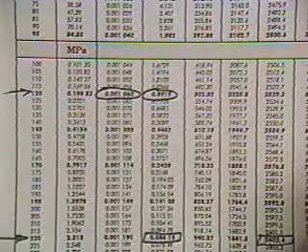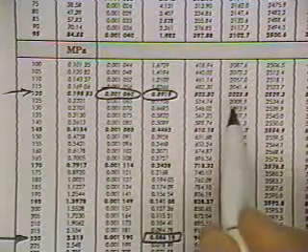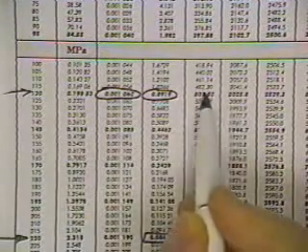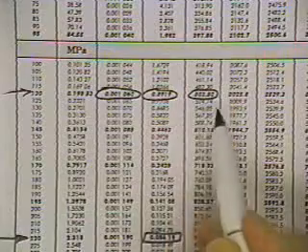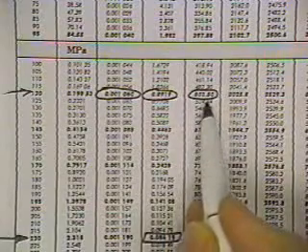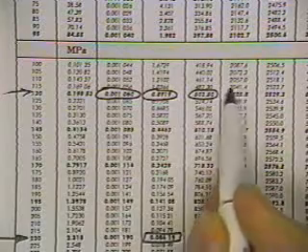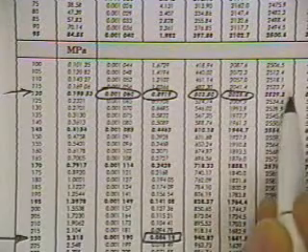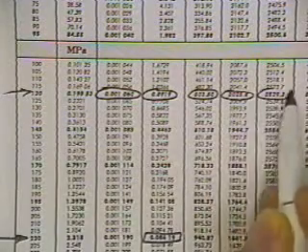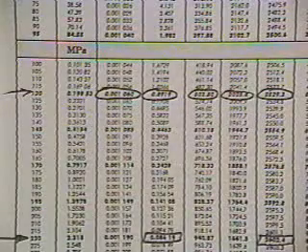Since we know we'll have to find information on the internal energies, we might as well pick those off too. UF is 503.5 at 120 degrees, UFG is 2025.8, and UG is 2529.3. So we found that information from the thermodynamic tables on page 48.